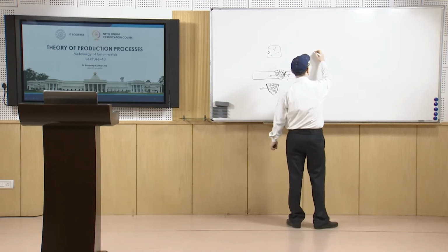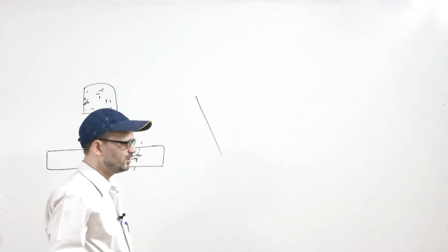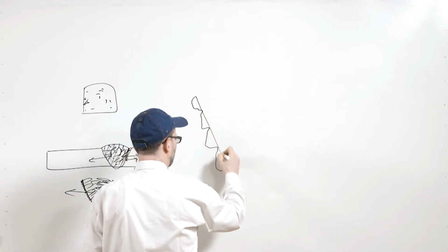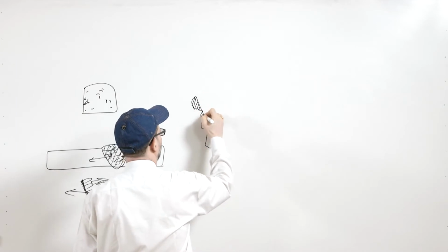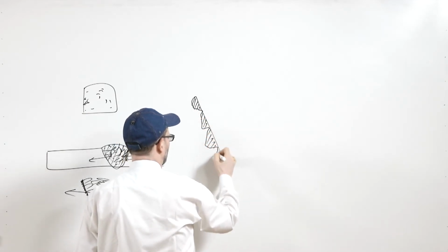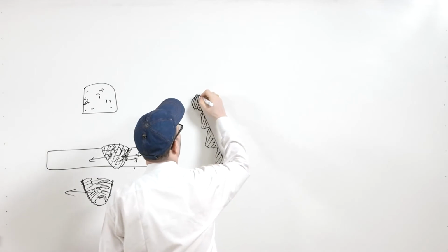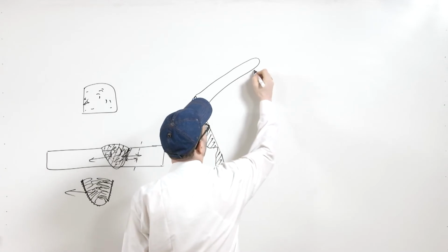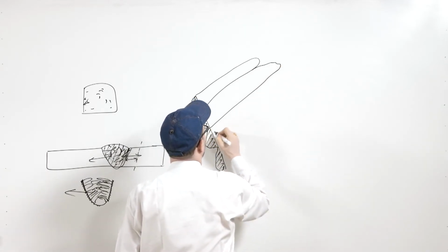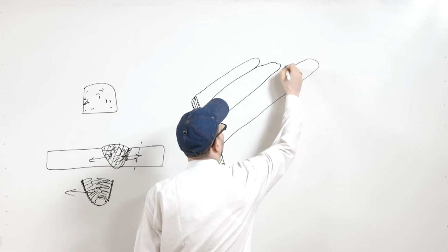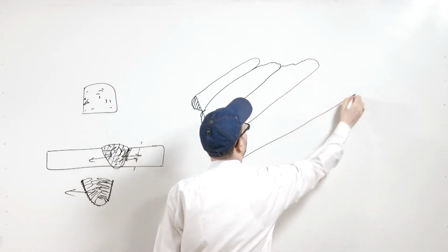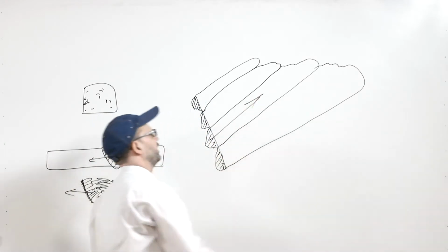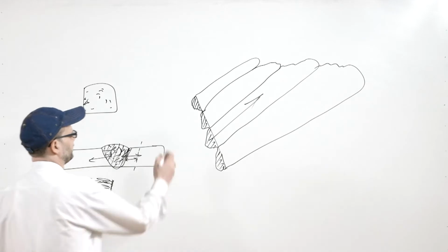So, what we see is that this is the fusion line, and this is how your grains are, and these are the partially melted ones which act as the nuclei. From here it will move like this, and now this will be like that, similarly like this. This way your growth of grains moves in that direction, and on this side you have the HAZ.